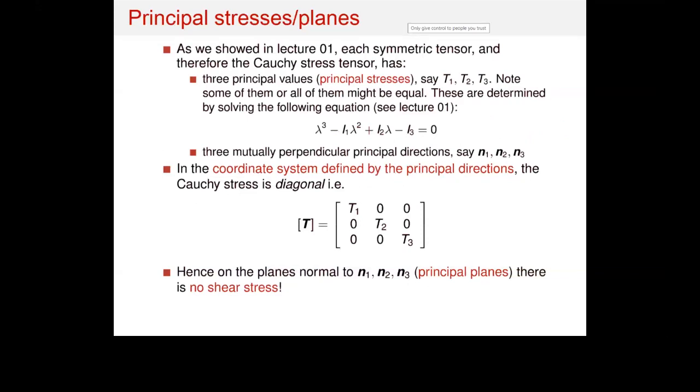The other thing we have about the stress vector is the principal stresses. The principal stresses are the eigenvalues of the stress tensor. So if you have the stress tensor T, you calculate the eigenvalues, just the values of lambda, and these are the principal stresses. Now, these principal stresses are the maximum normal stresses this stress can attain at any plane. I'm going to explain it in a minute, but I want you to get yourself familiar with the numerical procedure, and then we can see what these values mean.